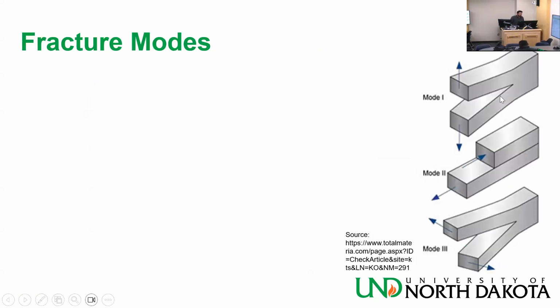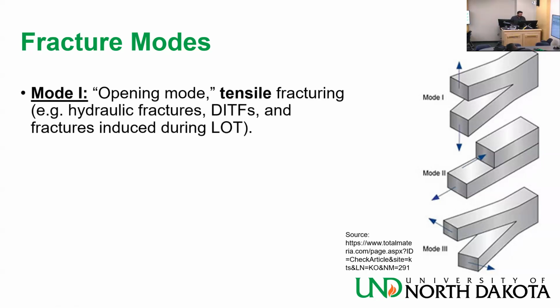Okay, there are 3 fracture modes. If you took a class on fracture mechanics, you will have learned about those. This is mode 1, the tensile, the open mode. Imagine taking chopsticks, flipping them around and pulling them apart. That's the tearing mode, the open mode. This is the kind of fracture we are dealing with when we are doing hydraulic fracturing, leak-off testing, and drilling, the drilling-induced tensile fractures that we learn in geomechanics and advanced simulation techniques, etc. That's mode 1.